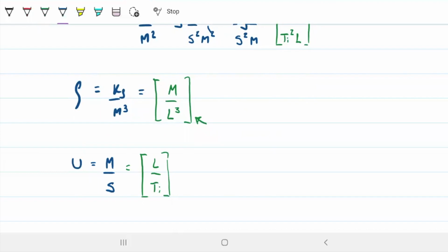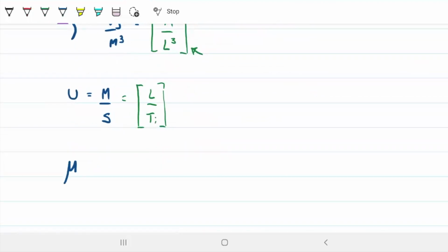Next, we have viscosity. If you guys just remember the table we were just looking at before, dynamic viscosity is given in newtons times seconds over meters squared. Then we can convert newtons into kilograms meters per second squared, and that will be over this guy here, so we can eliminate the seconds and that top mass there.